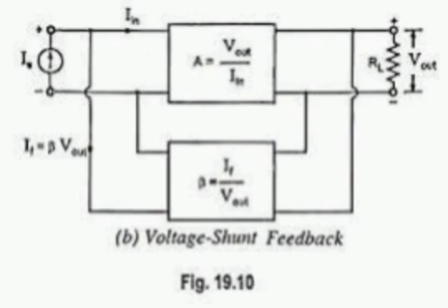Class B operation. Collector current flows for only 180 degrees of the AC cycle. Q point is located approximately at cutoff on both the DC and AC load lines. Collector emitter voltage at Q point VCEQ equal to VCC by 2. AC load power of a Class B push-pull amplifier PL equal to VPP square by 8 RL. Output signal is half sinusoidal. Quiescent power dissipation of power transistors is almost zero. The maximum efficiency of Class B amplifier is 78.5%.